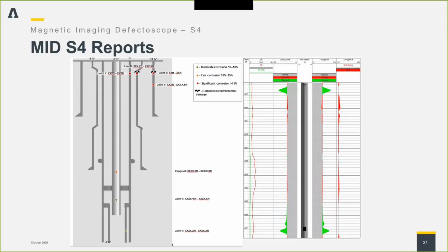that's the thickness. The curve on either side of the well sketch is specifically only for the tubing. So the green section is where it's bigger than nominal calculated. So that's the collar. And then we just reference the nominal thickness of that particular grade of tubing, and if the thickness calculated is below that, we shade it red. So that's on the thickness side of it in absolute inches.